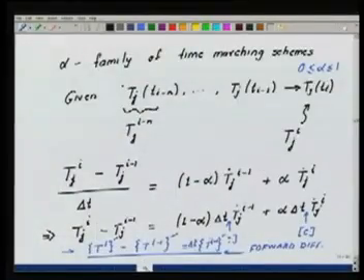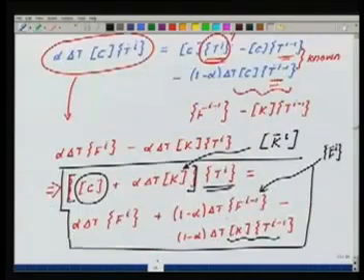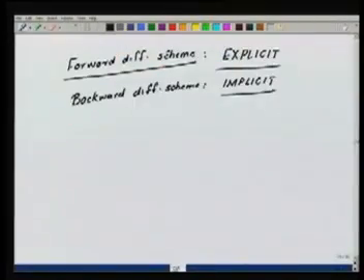The bottom line will be that when we do all this business of inversion and manipulation, then we have to apply the boundary condition. That is, we have to force T1 at time station I to be equal to the known value at that station, which again comes through the K hat matrix.